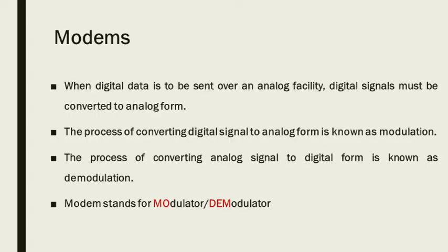Now we have to focus on the topic of modems. When digital data is to be sent over an analog facility, the digital signals must be converted to analog form, and the process of converting the digital signal to analog form is known as modulation, and the process of converting the analog signal to digital form is known as demodulation. So modem stands for modulator and demodulator. So that's regarding the definition of the modem.